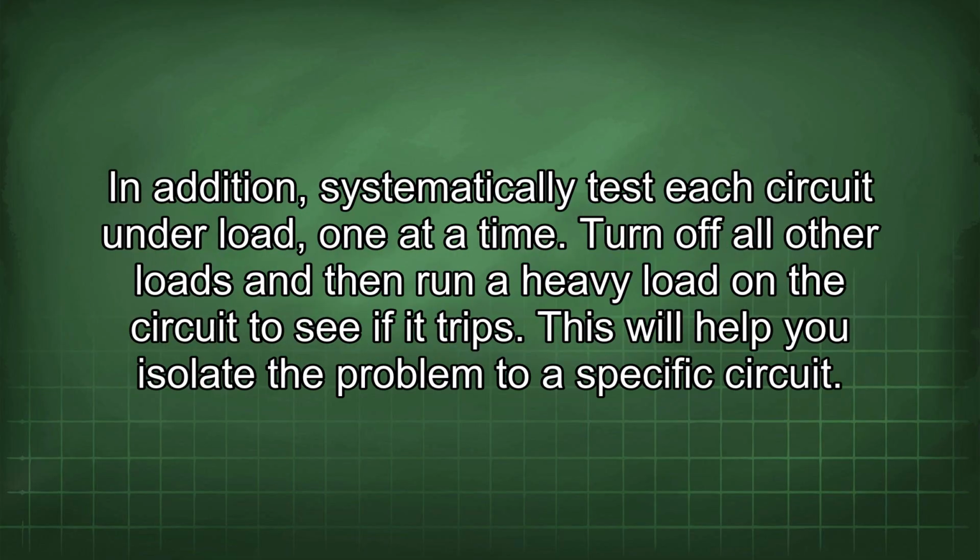In addition, systematically test each circuit under load, one at a time. Turn off all other loads and then run a heavy load on the circuit to see if it trips. This will help you isolate the problem to a specific circuit.